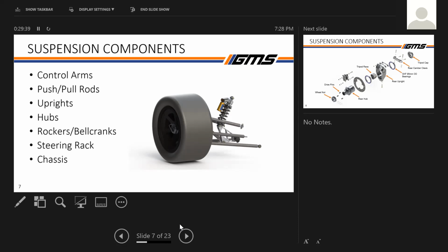It also goes into how you package things and how easy it is to work on. Push is generally easier to package. Not in this case for the front of the car because we just recently switched to the carbon fiber monocoque chassis. We could cut into the chassis and mount the bell cranks and dampers up high, but it's a lot harder to package.